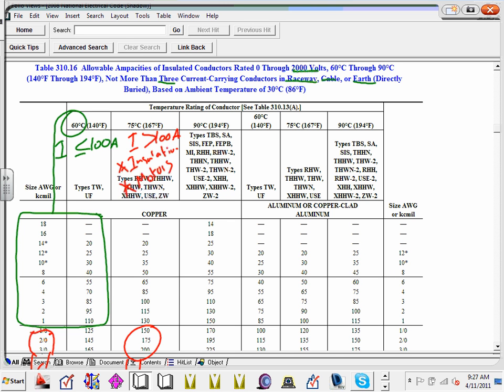So Brad, my friend, if you have a piece of machine and the machine is 60 amps and all the lugs are rated for 75, you know, you bought it. The lugs are rated 75, the cables are rated for 75. If you know that, then yes, the machine is less than 100, but you can use 75. Unless you know that the lugs and the conductors and the machine they're going to feed are rated for 75, that's what your default is.